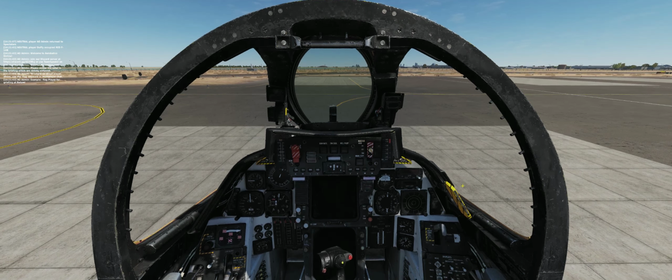Okay. ICS comm check. Roger that. Okay, ready? Check landing gear indication extended and transition light off. Select LTS on master test switch and verify all lights illuminate.